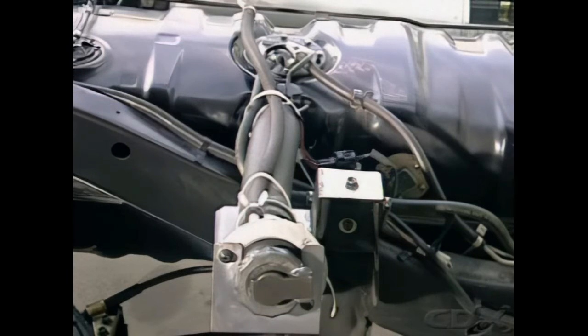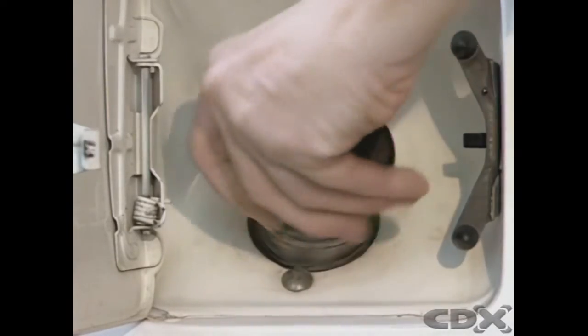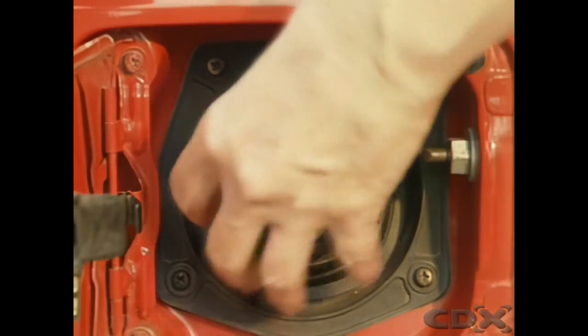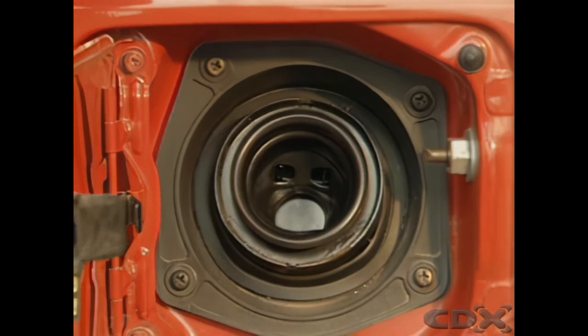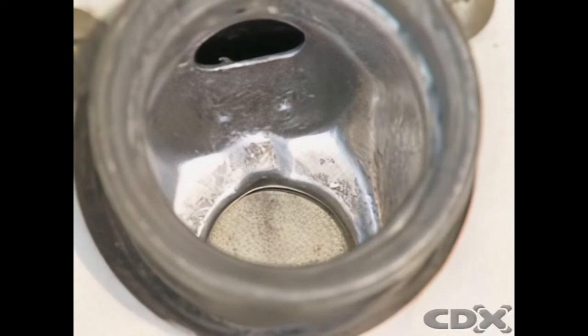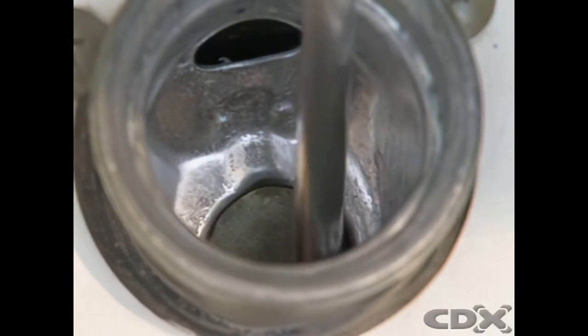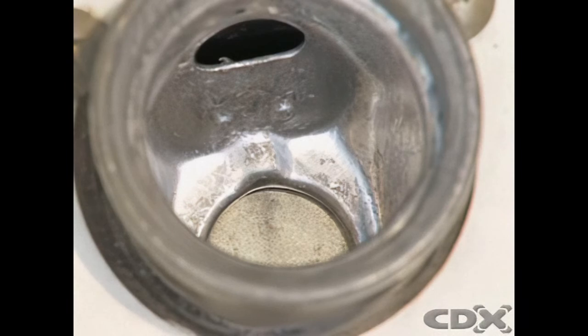The fuel filler is where fuel enters the system. The filler neck is a pipe that extends above the fuel tank. On unleaded gasoline vehicles with catalytic converters, the filler neck is designed to prevent leaded fuel being added. Its diameter is smaller than those on leaded vehicles, and a trapdoor inside the filler can only be opened by the nozzle of the unleaded fuel spout.